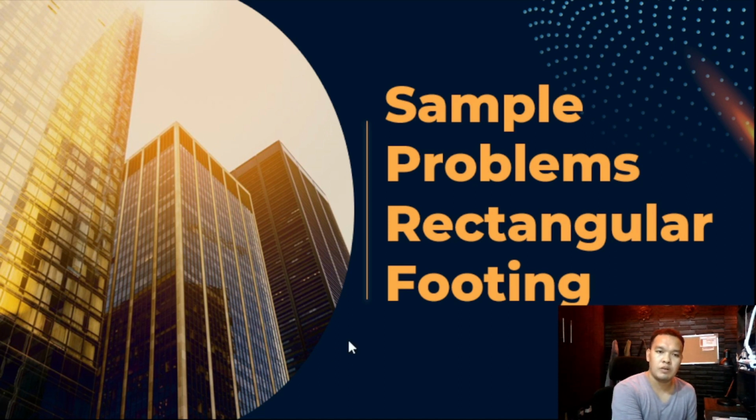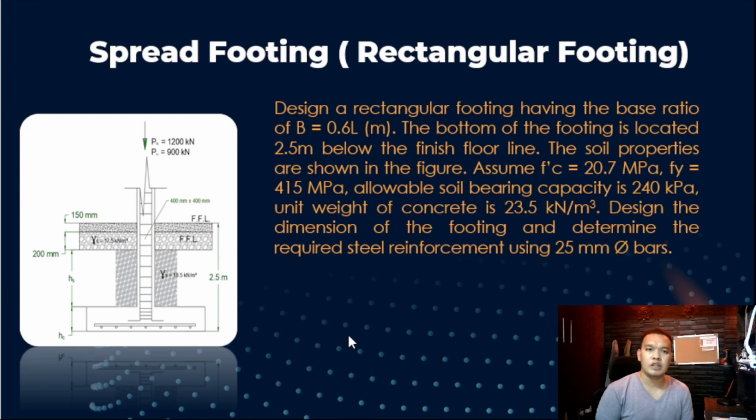So we have here problem number two for the rectangular footing. Design a rectangular footing having a base ratio of B is equivalent to 0.6 of L in meter. The bottom of the footing is located 2.5 meter below the finished floor line. The soil properties are shown in the figure. Assume F prime C is equivalent to 20.7 MPa and Fy is 415 MPa. Allowable soil bearing capacity is equivalent to 240 kPa. Unit weight of the concrete is equivalent to 23.5 kilonewton per meter cube. And design the dimension of the footing and determine the required steel reinforcement using 25 diameter bars.